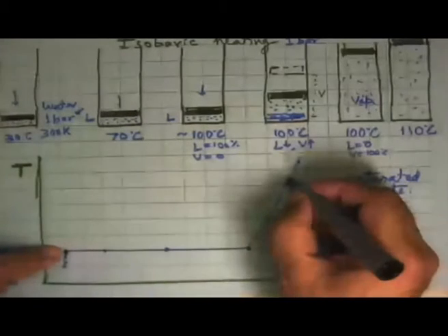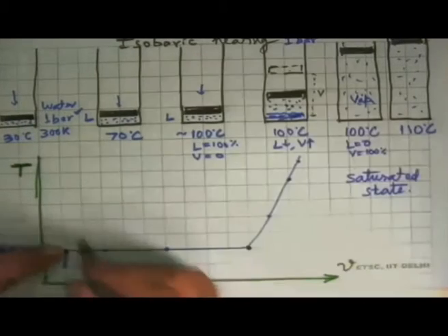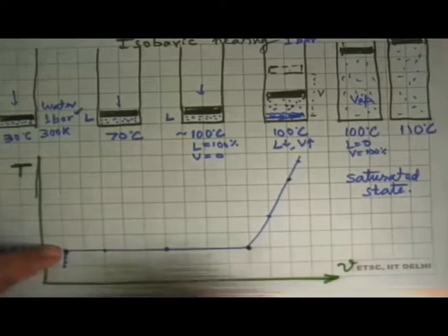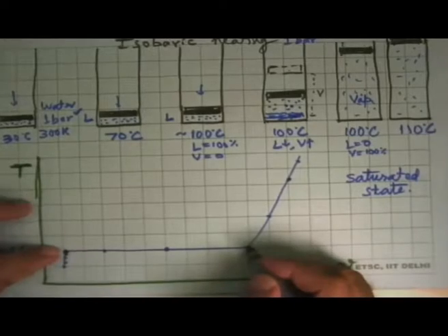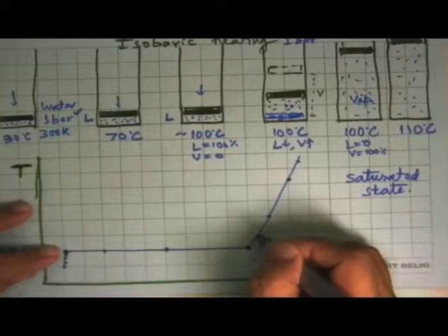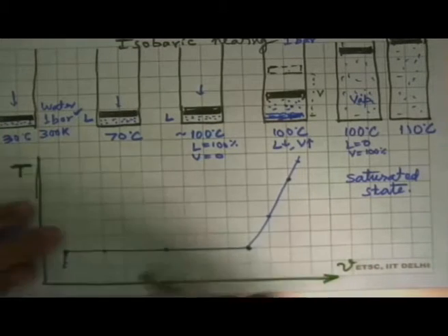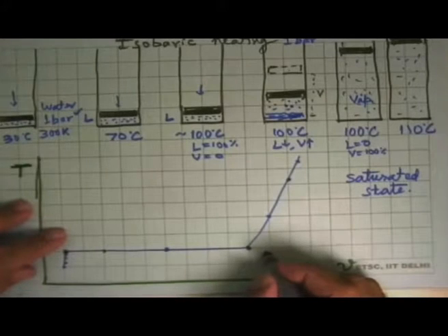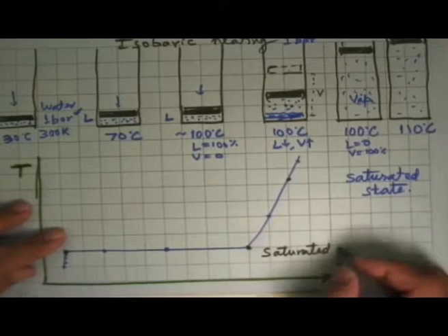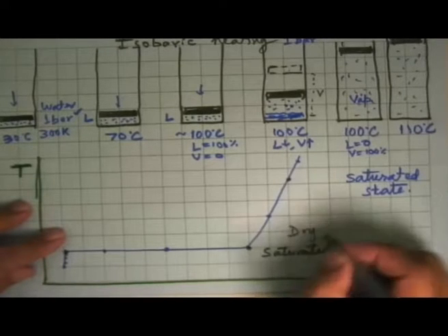This is quite different from a point like this. You heat it, temperature goes up. You cool it, temperature goes down. Same thing here. You heat it, temperature goes up. You cool it, temperature comes down. These 2 points don't behave like that. So this is a point where you have vapor, where heating makes the temperature go up, else cooling makes the temperature remain the same but causes phase change. This is called a saturated vapor. Or sometimes dry saturated state.